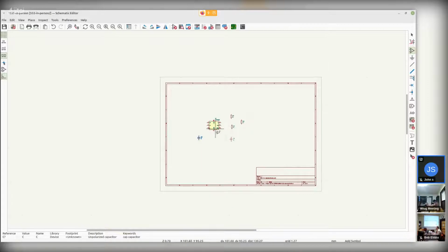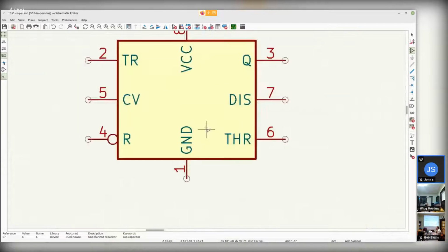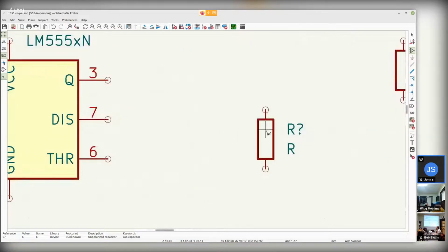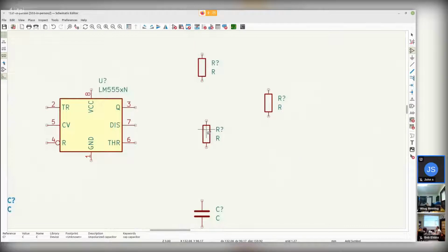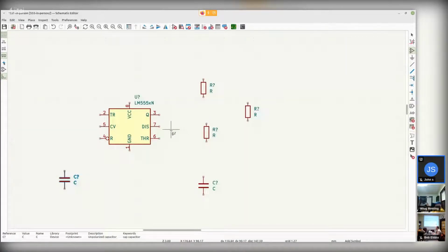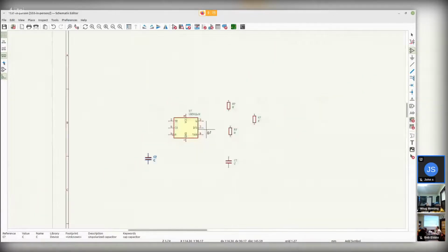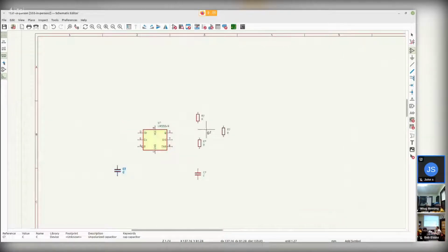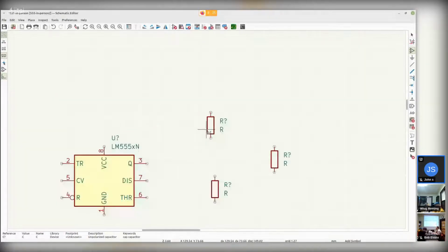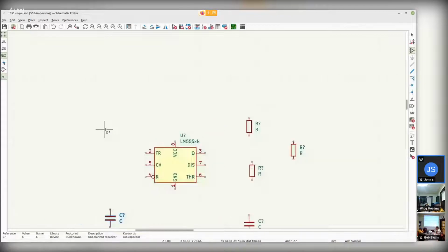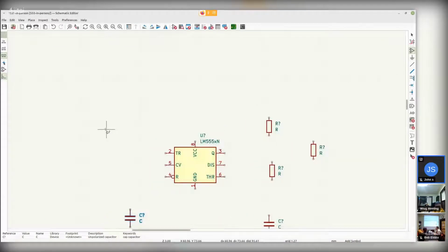You can zoom out with F2, and F1 will zoom in wherever the mouse is. See how it's centered on the mouse there? So I can move my mouse over something and then zoom in. I also think your scroll wheel zooms in too. It does, so the scroll wheel will zoom like the F1, F2 keys. And then panning is Control sideways. No, there it is. You can pan with Alt up and down as well.